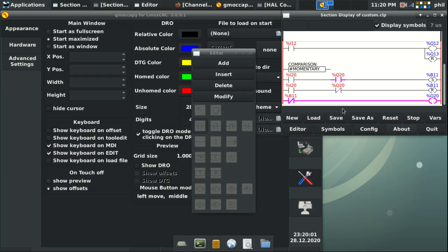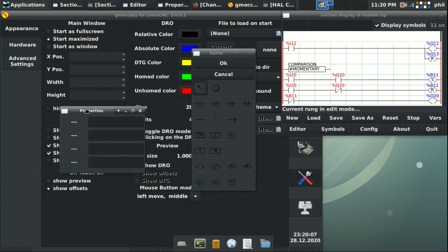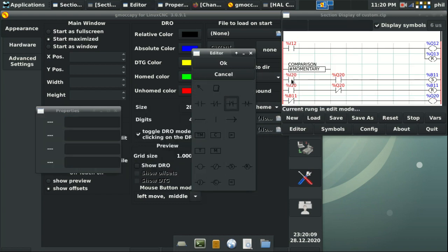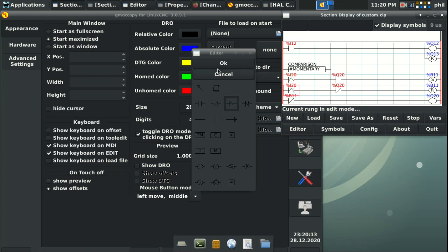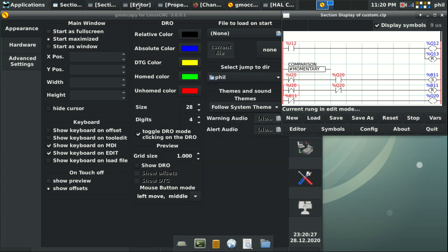So to alleviate that, what we could do is change the standard input of I-20 to, in this case, a rising edge input. Now, rising edge input thinks that the switch is normally open, and it waits for a close signal, and once it hits that close signal, it peaks and it drops. So it's a very short burst of momentary I/O, basically.